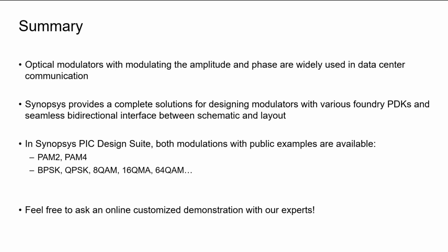Synopsys provides a complete solution for designers to design the modulators with various foundry PDKs, and also we provide a bidirectional interface between schematic and layout. That is, you are able to use the schematic in OptSim Circuit and design the schematic by the simulations. Export your design to Optical Designer for layout generation. Besides, in Synopsys PIC Design Suite, both modulations with public examples are available, like PAM2, PAM4, BPSK, QPSK, 8-QAM, 16-QAM, or even 16-QAM example.